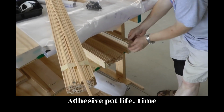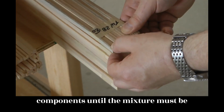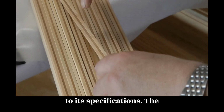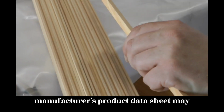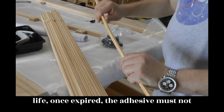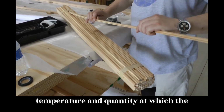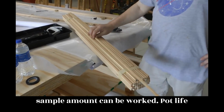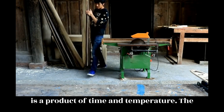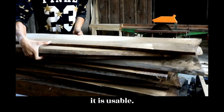10. Adhesive pot life. Time elapsed from the mixing of the adhesive components until the mixture must be discarded, because it no longer performs to its specifications. The manufacturer's product data sheet may define this as working time or useful life. Once expired, the adhesive must not be used. It lists the specific temperature and quantity at which the sample amount can be worked. Pot life is a product of time and temperature. The cooler the mix is kept, within the recommended temperature range, the longer it is usable.